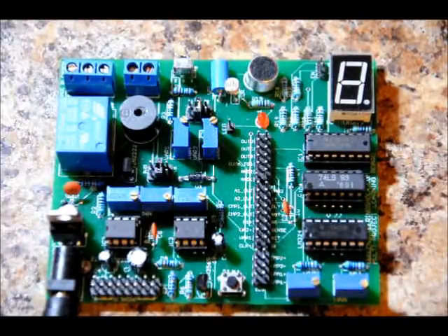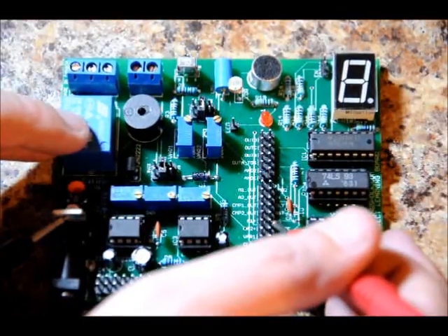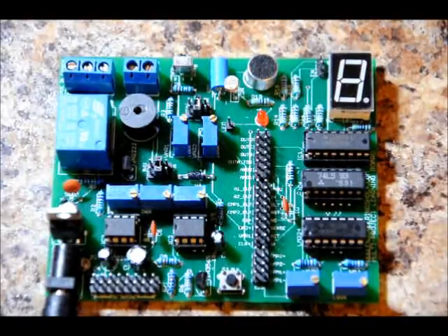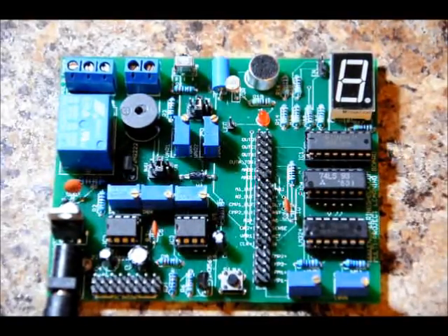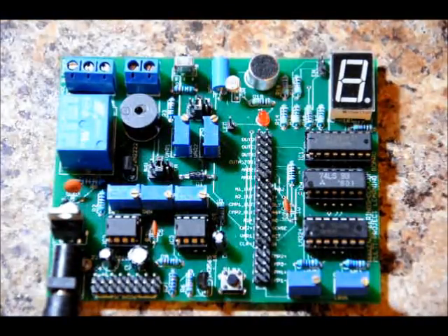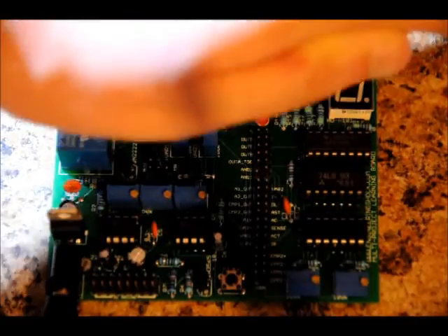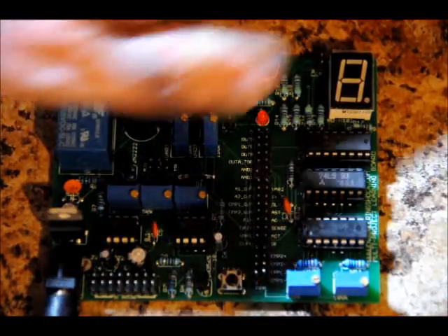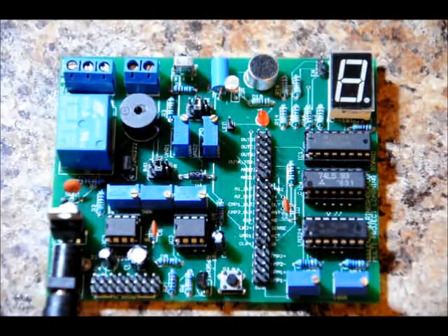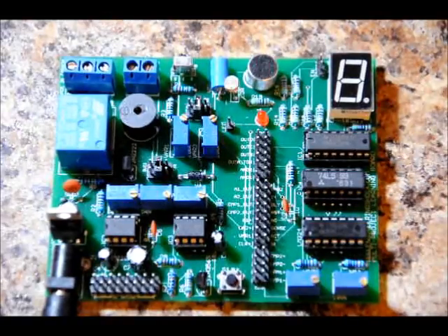Now there's not a lot of light hitting it right now, but I can have a quick look and read 0.67 volts in light, which is what we expect. We expect the voltage to be much higher in darkness when I cover the LDR. So actually, what you can do is take your positive lead, place it on the sense line, and see how the voltage changes based on how much light is on your LDR, which is right here, that little orange thing.